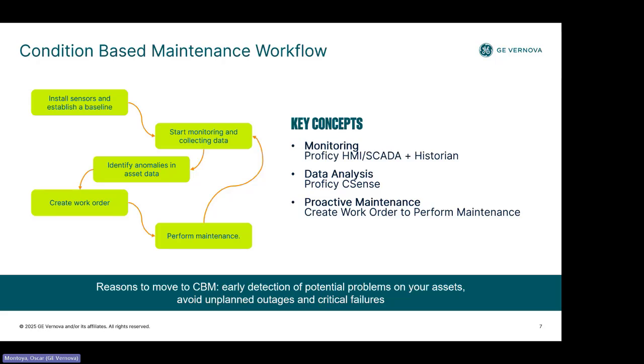And also, once you have that data collected into your Historian, it will give you the ability to give contextualization of the data. And also with Proficy Sense, you will have another tool to identify those anomalies. And then from there, with these two tools, you can enable proactive maintenance. And then in that way, with planned time, you can create work orders and perform the maintenance.